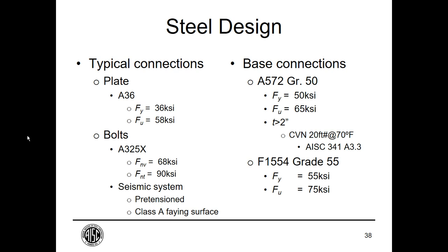We will use anchor rods, Grade 55 anchor rods that are weldable per Supplement S1. So if you want weldable anchor rods, you have to specify Supplement S1 for Grade 55. Grade 36 anchor rods are always weldable, and the Grade 105 are never weldable. But 55 can be weldable if you specify the supplement.